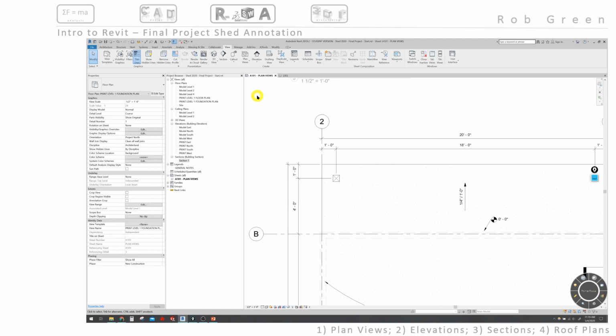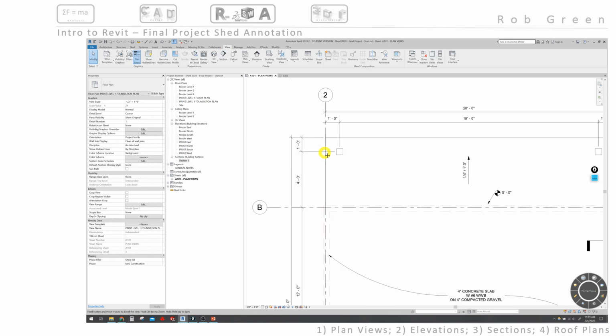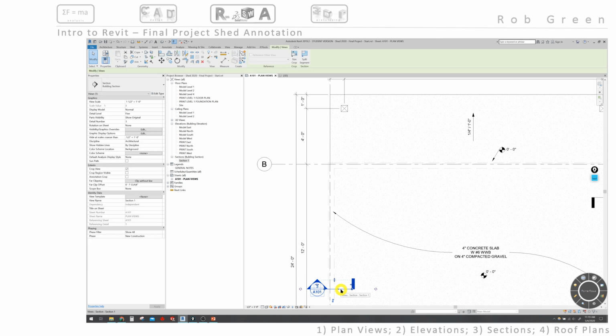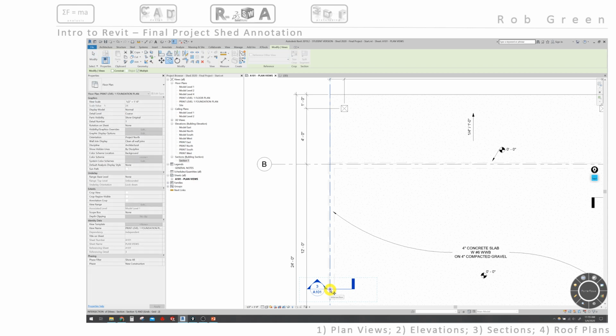So actually, I think what I will do is create it via an alternate method, just because, well, I can. And here's a video to show the different types of ways to create objects. I am simply going to select the original view callout that it created and copy it, from its current location up to a location that is on the same spot, and click it into place. Hit escape a couple times.